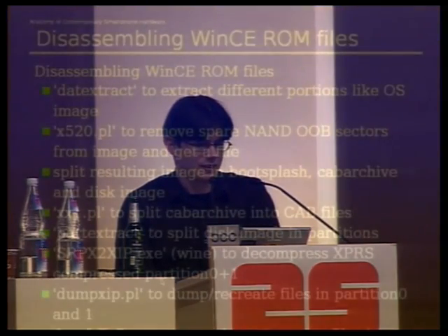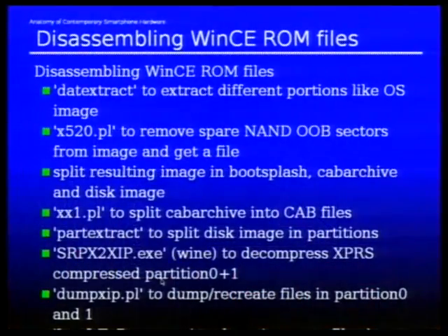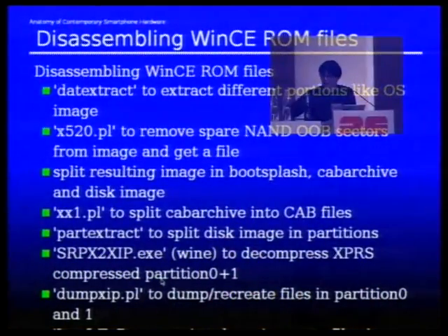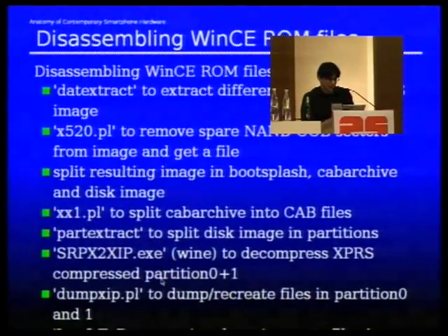Time is running quickly. Obviously, what you can do is disassemble the drivers. Before you can disassemble, as in assembly language, the drivers, you actually have to disassemble, as in unpackage, the Windows CE ROM files, which is a very unpleasant exercise. These are the various tools and scripts I had to use for the Glofish, which meant spending a day in the hex editor and trying to figure out what they did.